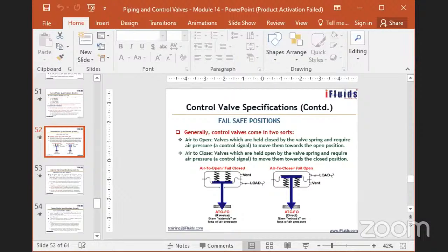These valves usually come in tanks. In tanks we use a nitrogen atmosphere to keep the tank vapor space in inert conditions. So continuously nitrogen will be coming in and there will be some bleed also. In those lines we put the SAPCV. It is called self-actuating pressure control valve, SAPCV.